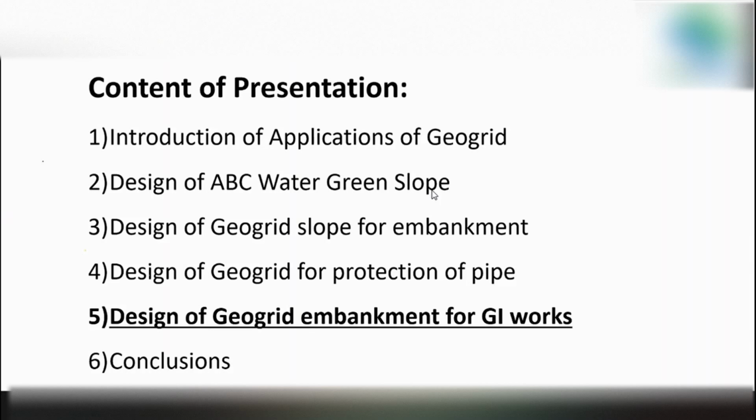But there's no choice, right? You either build a very expensive retaining wall to have a clear cut edge, or you let the soil actually slope down naturally, but it just takes up space. But sometimes you do not have the luxury of the space for the surcharge to actually slope naturally down.